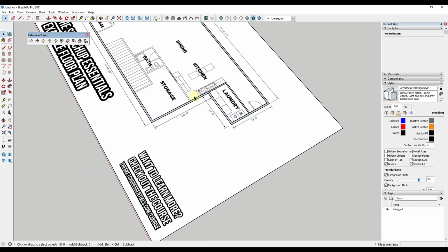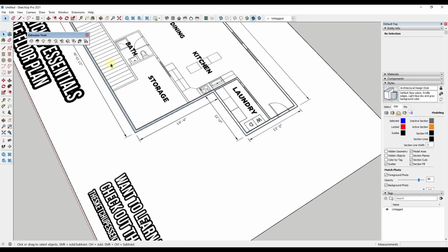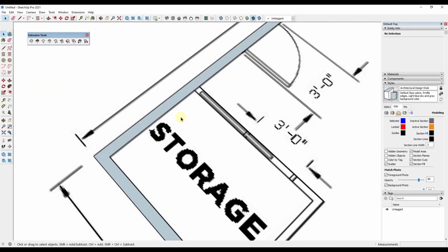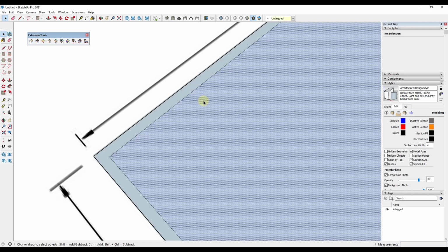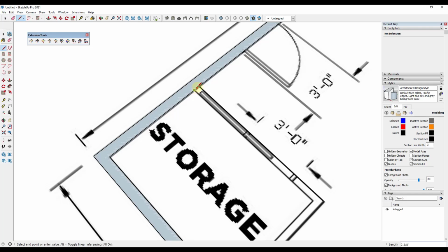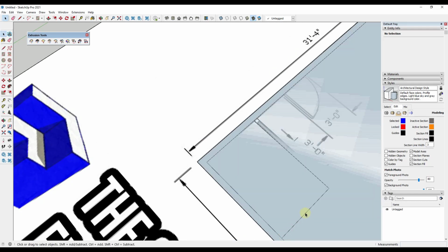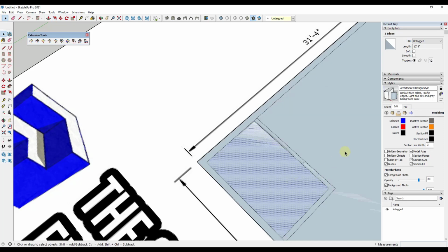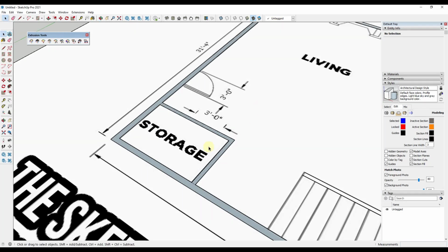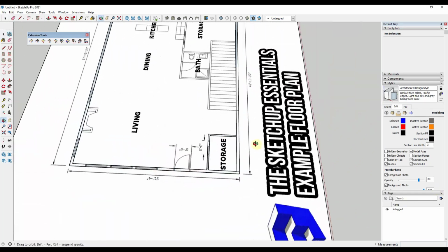And all we're going to do is keep roughing all of these walls out. So for this one, for example, I'm going to draw a line over here, and I can see how this is about 5 foot 2 inches. So I'm just going to type in 5 foot 2 and hit the enter key. I'm going to delete this face out. I'm going to do the same thing. And so for this one, I can go ahead and draw a 7 foot 6 inch line over here. And in this case, I would offset these out using the offset tool by 4 inches. So notice how I'm able to draw that wall in here really quickly.